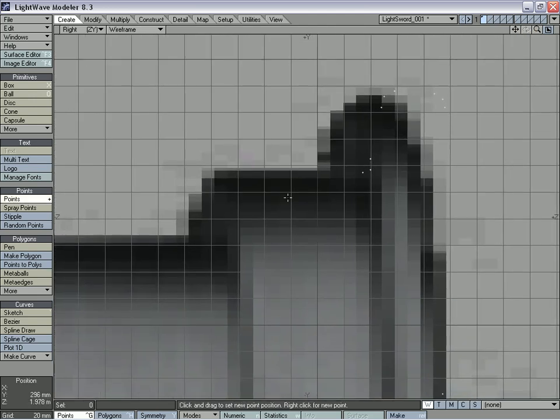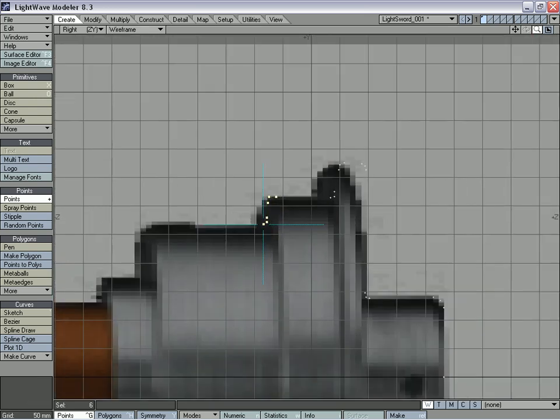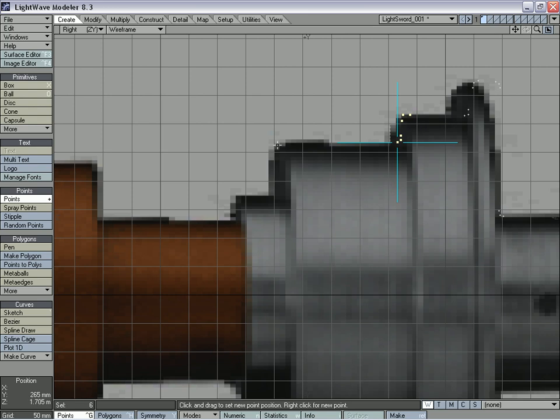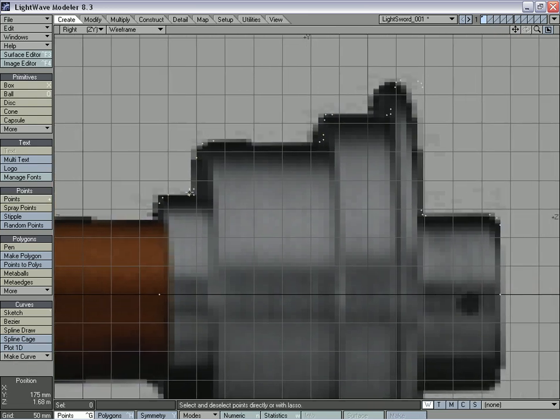Alright, now Shift and plus again to reactivate the points tool, and we're going to create 3 points right there and come down here. And right now we're just laying out basic points. These don't have to be very precise, we just want to get the points down, and then we're going to go and edit them in just a sec. And now the less rounded I want it, the more I'm putting the points closer together. Like right here, as you can see, it's going to be a much tighter curve than once you get up to here. I'm just going to go in and bring these in just a bit too.